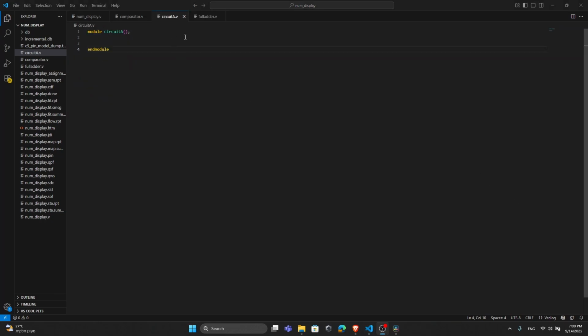Okay, now we are going to move to design the circuit A. But before that, the circuit A function, as I have explained before, we are going to add 6 to the input that we have, so we can transform the number from binary into a binary coded decimal. So we need an adder. We need actually 4 adders to make a 4-bit ripple adder. So to make that work, now let's design the full adder. Okay, and then go back to circuit A.